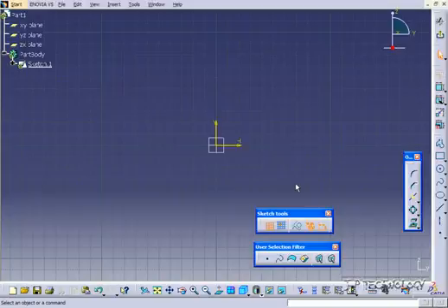What construction geometry is, is that we're able to create sketches, and from those sketches we're able to convert them to construction geometry. Now, the difference between a construction geometry and a normal sketch is that the construction geometry will have dotted lines, and when you go to create a part, it will not be included in the overall extrude or cut or whatever it may be that you're doing with the feature. So construction lines are just there strictly to make dimensions and make references off of.